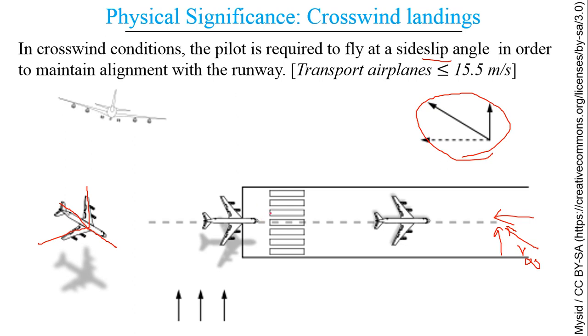Two different methods are used over here. Either it is the crab method, where the aircraft totally orients in this direction and also lands in this particular orientation. This is known as the crab method, as the motion represents a crab's walk. But this is normally not preferred, as when an aircraft lands like this, it may damage its landing gear, or in some conditions even cause accidents, as the aircraft will be totally tilted over.